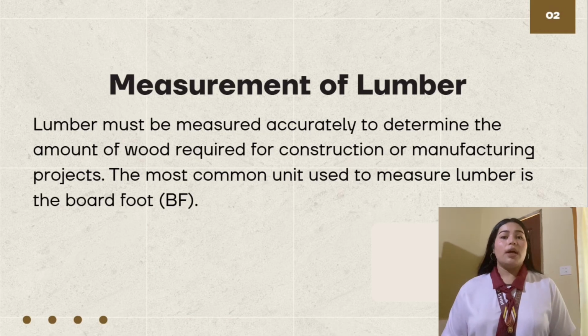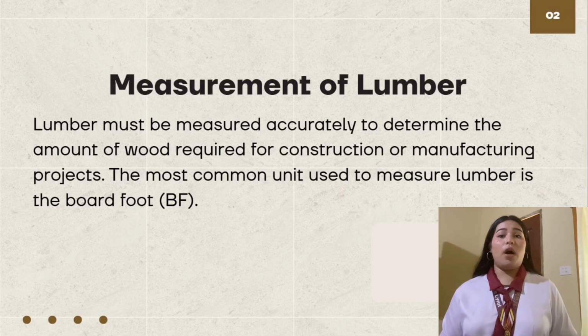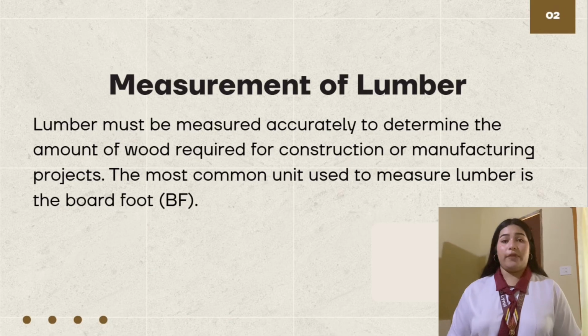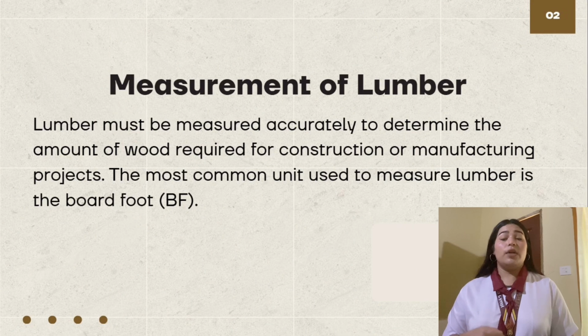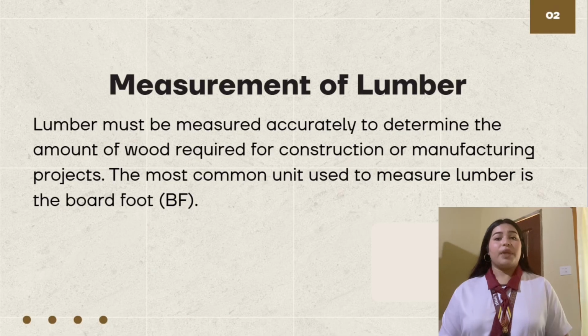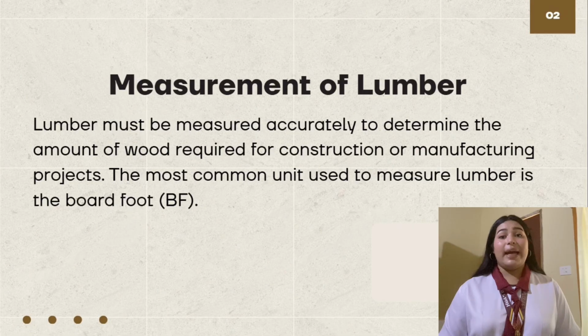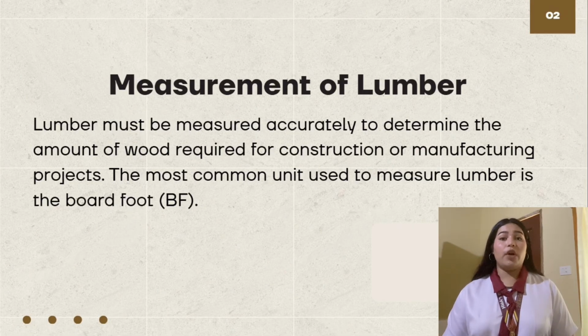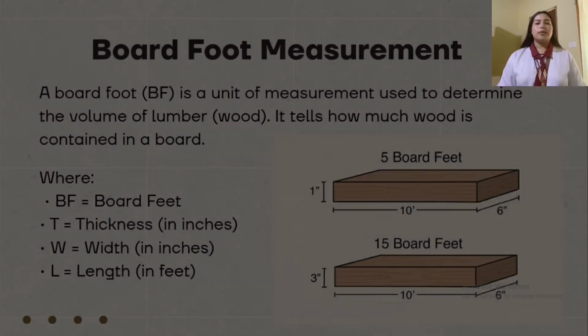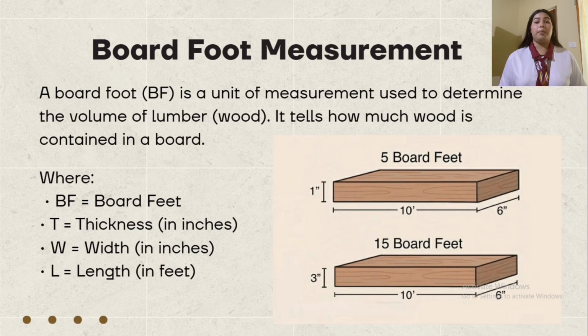Measurement of lumber. Lumber must be measured accurately to know how much is needed for a project. The most common unit of measurement is the board foot, or BF for short. It helps to calculate the volume and the cost of lumber. Accurate measurement ensures you get the right amount of lumber for construction or manufacturing, to avoid waste and extra costs. So now, let's proceed to board foot measurement.